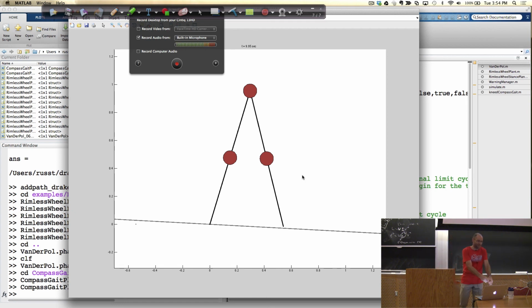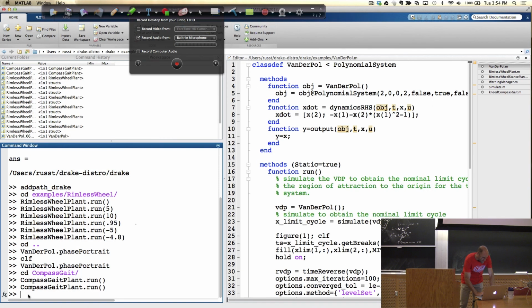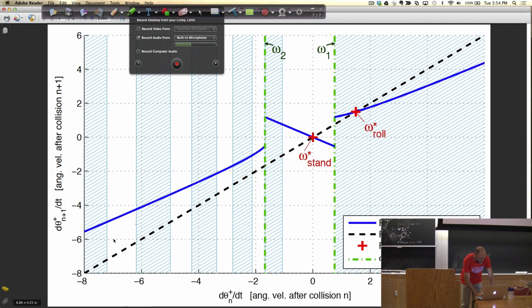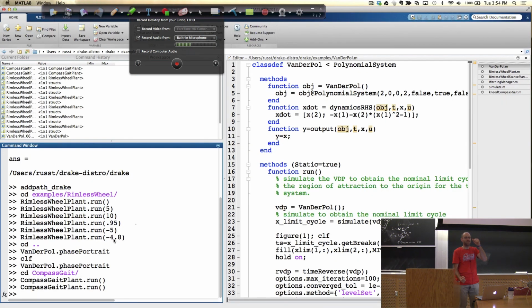And in practice, it's really hard to build these. We've tried, and they mostly just fall down. Especially to get the masses right, to make it all the mass collected at the hip and a massless leg, we've shattered so many robot legs because we tried to make the leg really light, and then we take a step and shatter the leg, and it's everywhere.